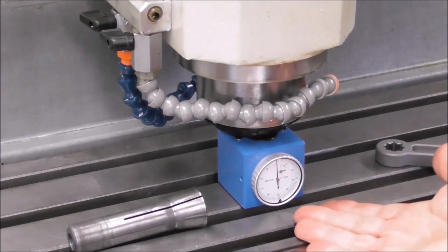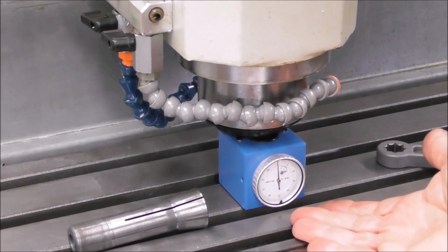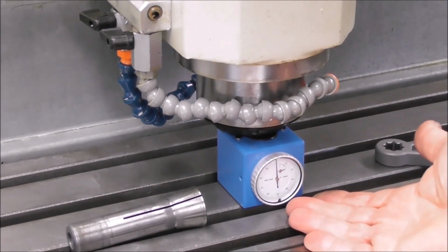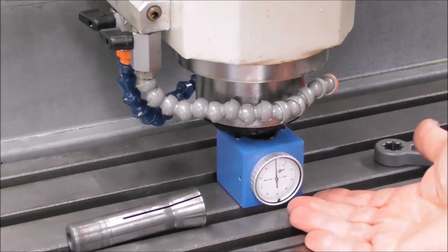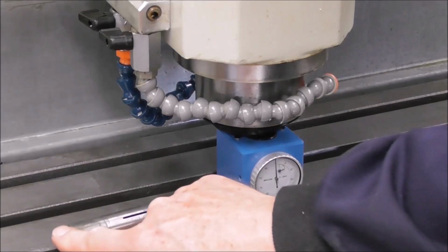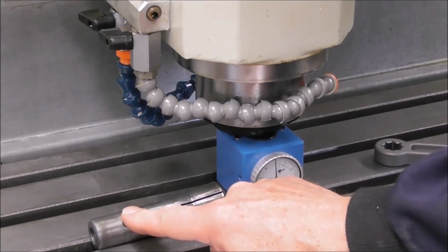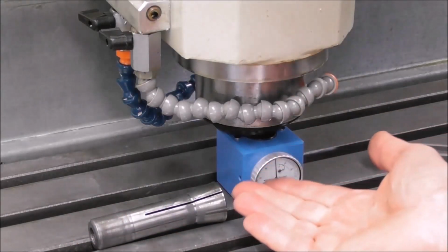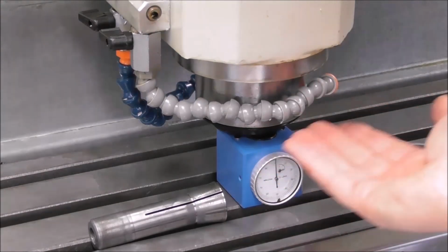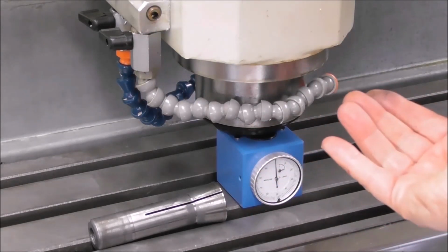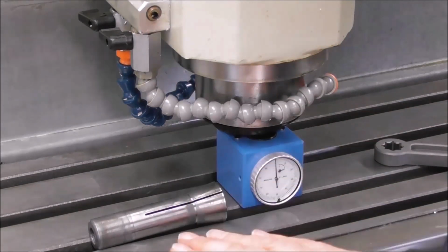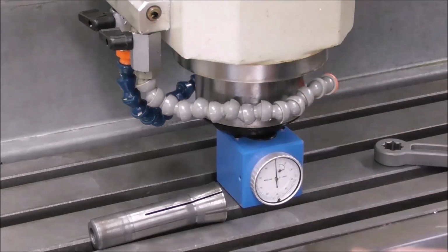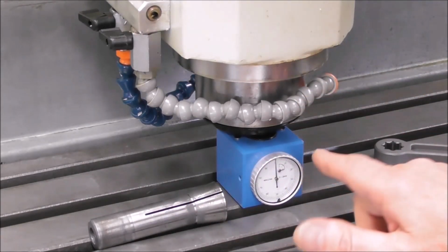So these mechanical dial indicator type tool setters have a lot of advantages. It's a good idea to take your TTS 3/4 inch collet out so that you're clear of the bottom, otherwise you've got to step it only half in. Better to take the collet right out, clean the bottom of the spindle nose, come down to 0.